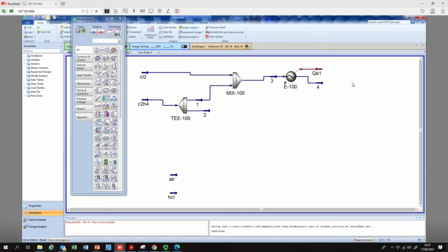We deleted the continuous stirred tank reactor and added a conversion reactor. This makes our life a bit easier, because it ensures 99% of our reactants are converted into products. And for this type of assumption, we don't need to add any rate kinetic expression.